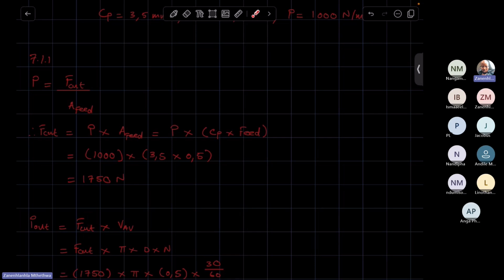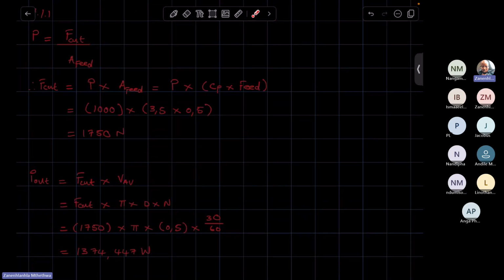This you've calculated. This will be pi dn. You have the diameter, you have the rotational frequency. So you substitute. Remember, this is in terms of revs per minute, so you divide by 60 to convert it to revs per second. You calculate this, punching it in your calculators, this is what you get.